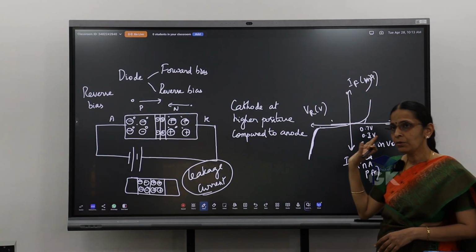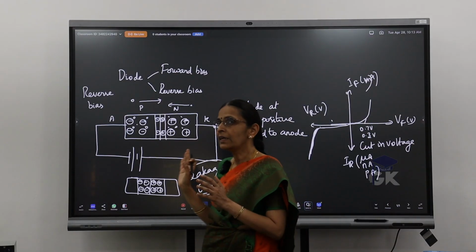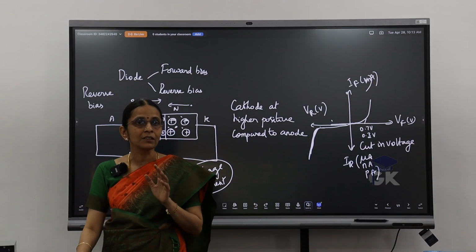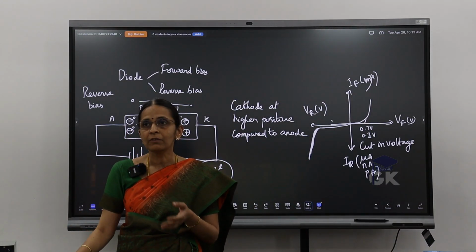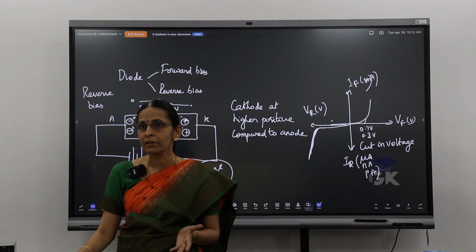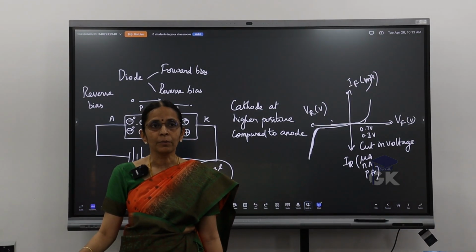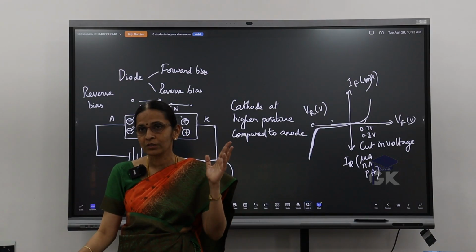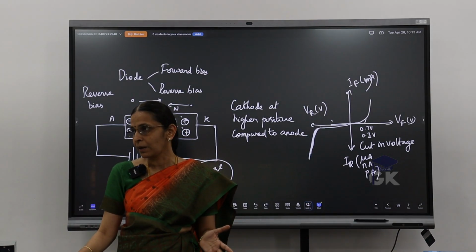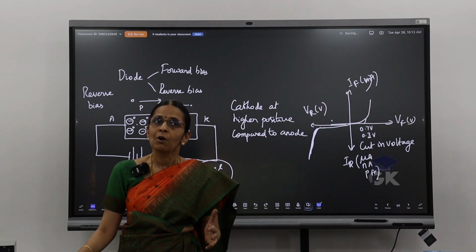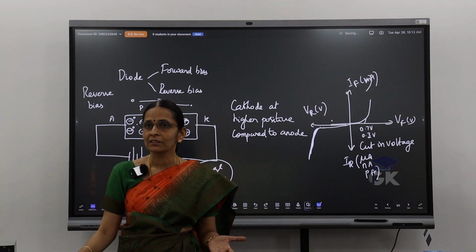We can see the diode data sheets. From the data sheets, we will come to understand what the reverse voltage is. For example, the 1N4007, which we are going to use here in our lab, can be operated till say 1000 volts before it breaks. Whereas in the laboratory, what is the maximum DC voltage that we have?